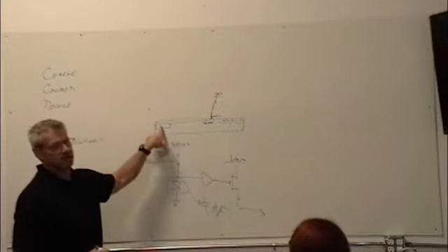What you would do is, light coming through, if it comes through where your transistor is, it's going to screw up your transistors. So you have to shield over the top of it. So you've got metal layers. If I say that this is the area of my pixel, what I found on mine was, using a 2-micron process, I think my pixels were about 50 microns on the side, if I remember right. And my diode was maybe that much of the area.